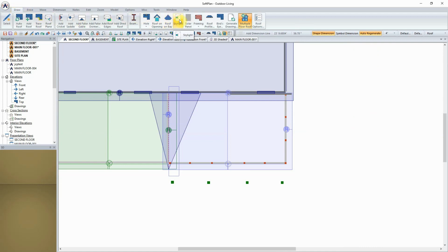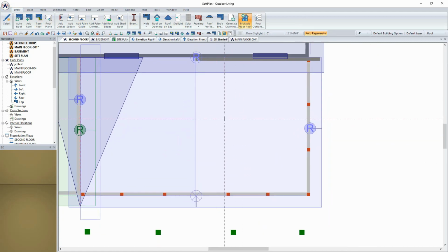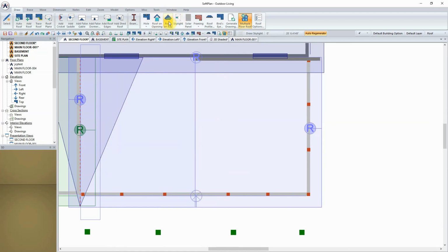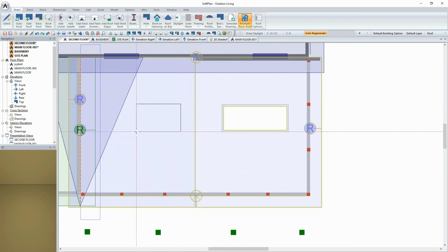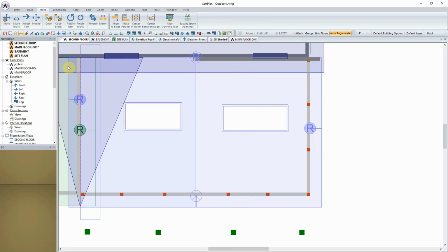As I do that, I can now come in through the draw and skylight option from the ribbon bar, which will now allow me to position my cursor onto the drawing screen, click to begin, and sketch in a similar way as to what I did with the solar panel option, a rectangular box. And the rectangular box will actually cut a hole at this stage through the roof and if there were a ceiling below in the similar way, so that we can actually have a skylight.